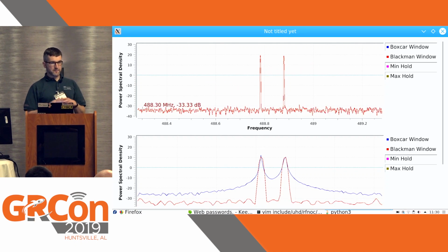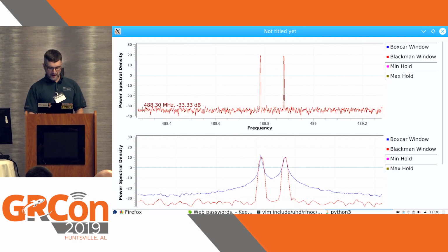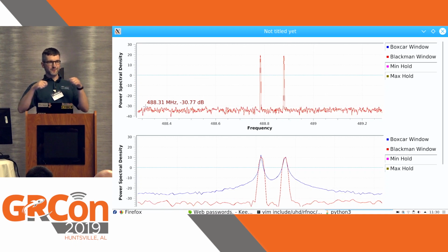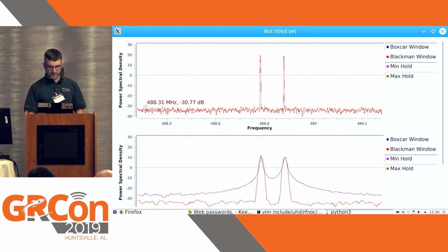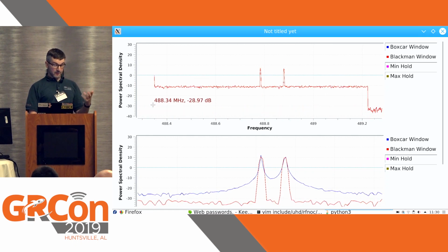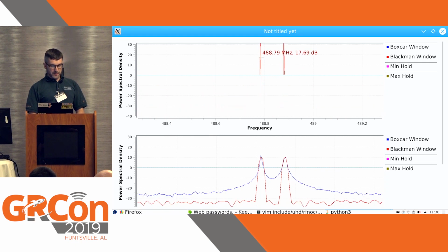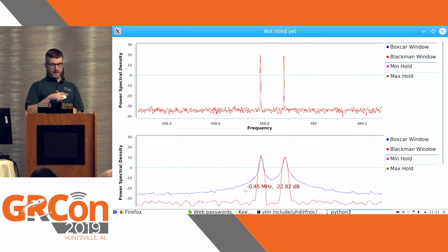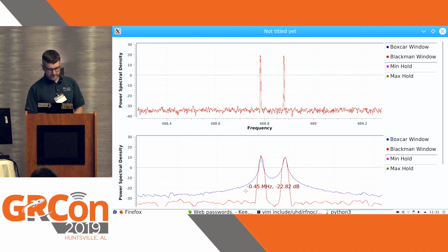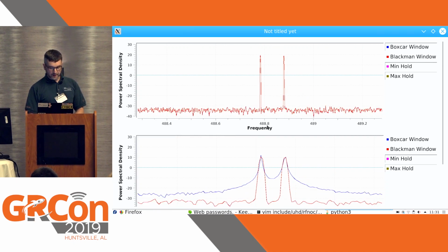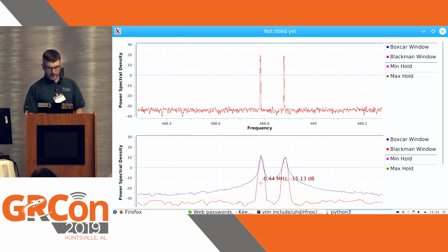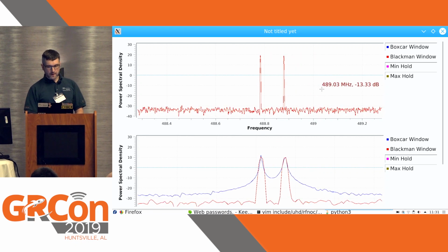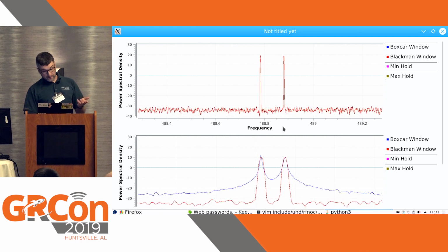But the noise will always spread out over all the bins. So I have more bins in the top, so I have to divide the energy over more bins, so it'll go down a bit. And another way to look at it is, this here is a pretty sharp line, whereas here it's not. If you think of it as integrating over the frequency domain, I'm basically putting some of the energy in this width, where here it's higher, okay? So that's one part of it.